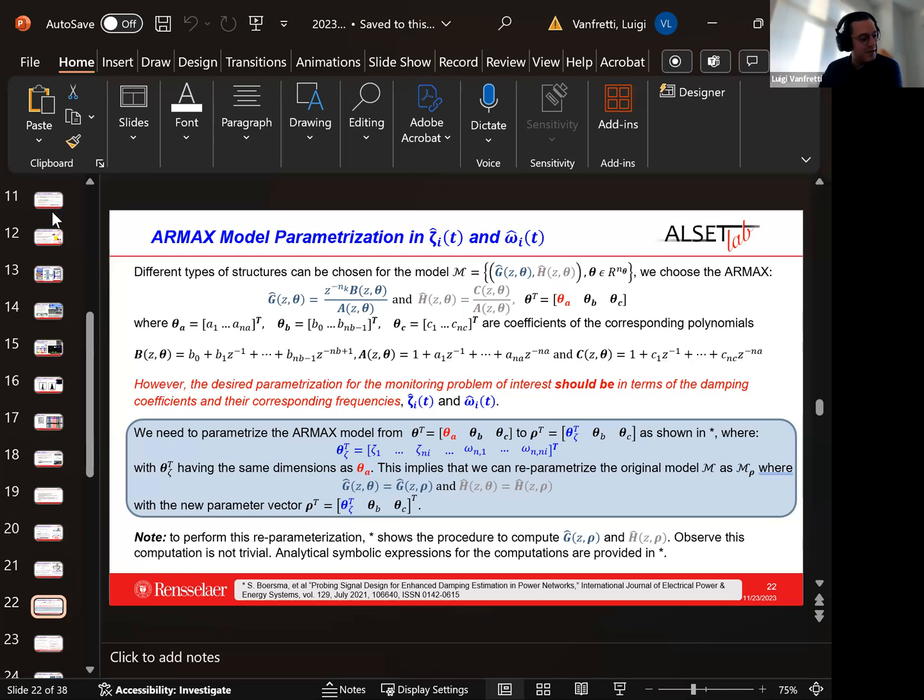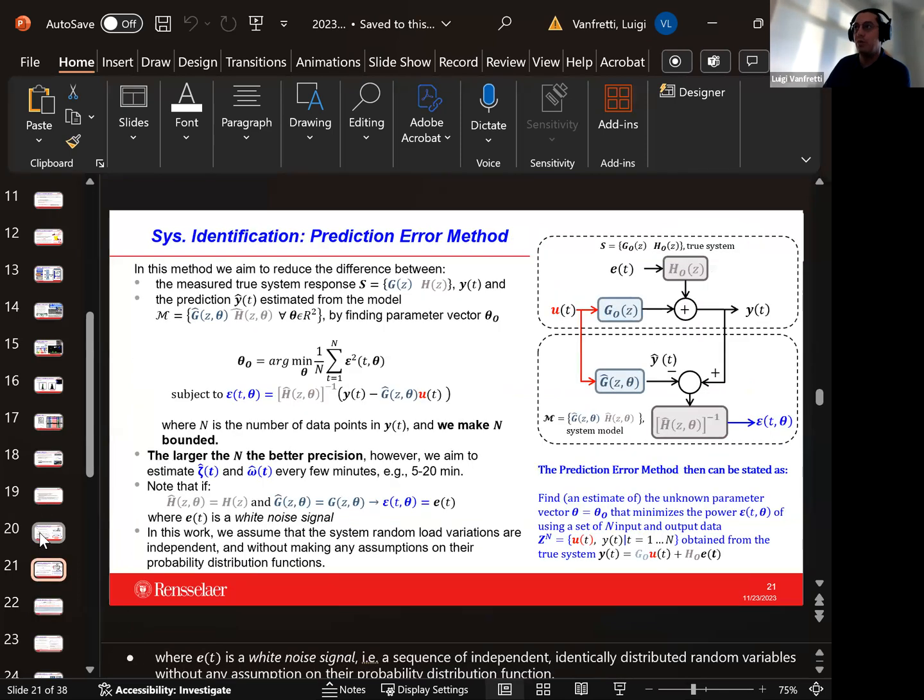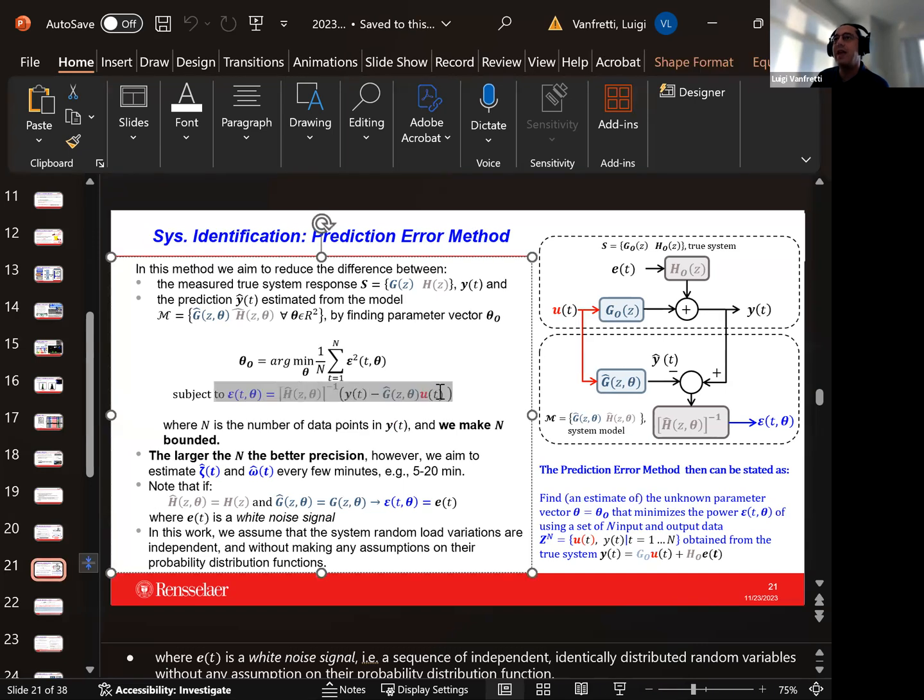The motivation is that we are assuming that the dynamics we're exciting from the random loads are exactly the same, and this is the error that you're trying to minimize. So if the poles are correct and your estimates are close to the real system, then this error could be zero. That's how I would respond, but I think Xavier could be better suited to answer this question.